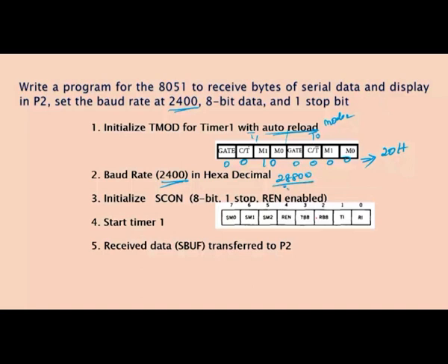28,800 divided by 2,400. The value is 12. Then 256 minus 12 is 244. The 244 is converted into hexadecimal by dividing by 16, right: one value, then again 8, 84. The remaining 84 is 5 times 16, remaining 4, right. So this is F, 15. The 15 is less than 16, so you can stop. So F 4. The corresponding value is F4H.